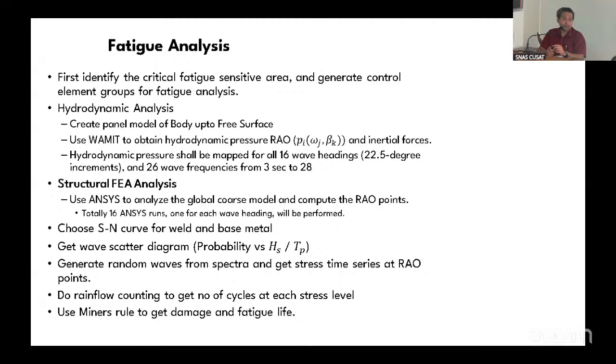And the key thing here is, if you're going to do fatigue, don't jump and say, I need to do the time series analysis in ANSYS, and that's going to take a long time. If you are clever, you can take shortcuts. You can just do maybe one static analysis, then use those numbers and do your calculation outside, which saves you a lot of time.